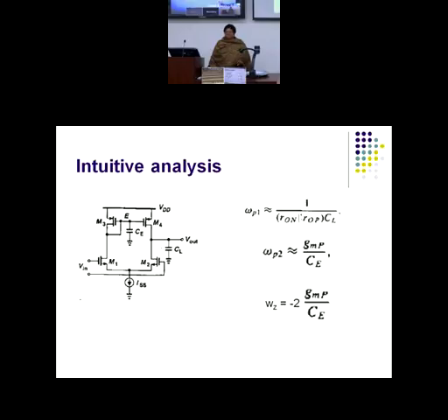Yes, go on, students. Every student should do it, otherwise you will never be convinced on your own. You have to see that the P node does come to negligible variations, which you can neglect in comparison to the other nodes. So you can assume very well that the P node is behaving like an AC ground, though it is actually not. So next time, everybody should come up with his or her own derivation.